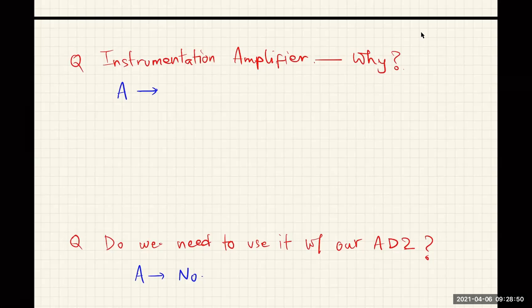So in that case, you would want just a single-ended voltage to measure. Or in our case, even if the oscilloscope did have a math mode, you want to plot an XY graph, and many oscilloscopes can only plot XY graphs using channel 1 and channel 2 of their input channels. Okay, so in that case, you cannot use the math channel to plot an XY of the current and voltage. And that is why for this lab, if you were working on some lab equipment that did not have a differential probe, you would need to use the instrumentation amplifier.